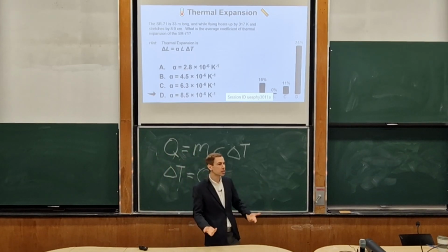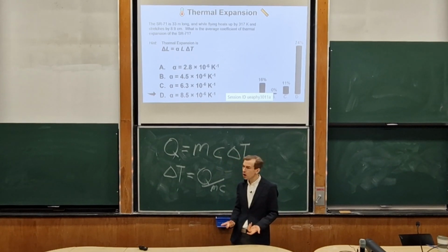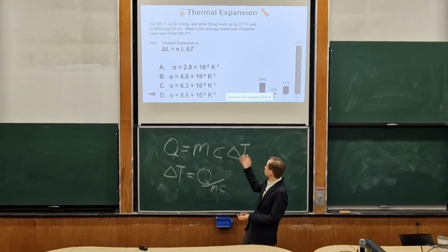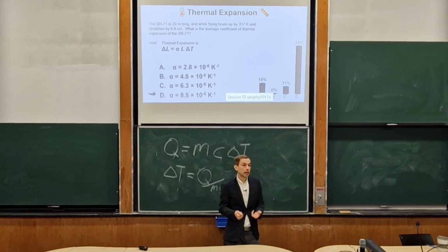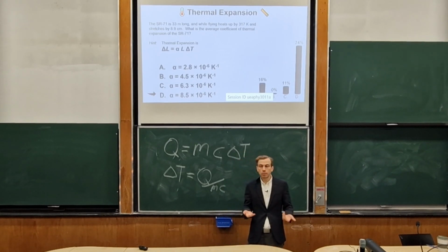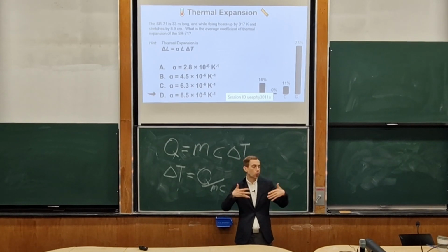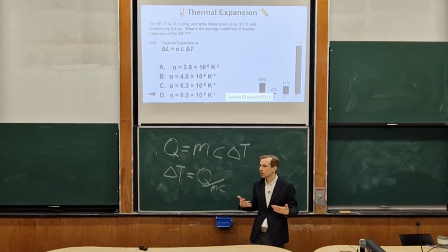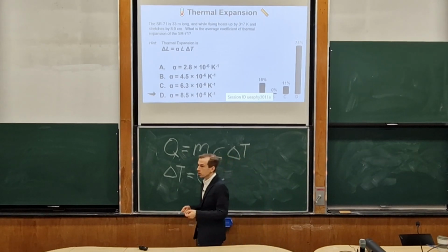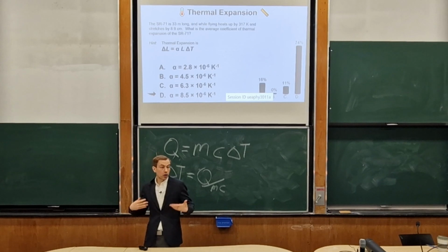So titanium is very expensive, it's very difficult to work with. But if your aircraft is going to heat up by this much, it's no good making it out of aluminium or something like that, because your whole aircraft might melt, and that would be very bad news for everybody. So based on how your aircraft's going to perform.